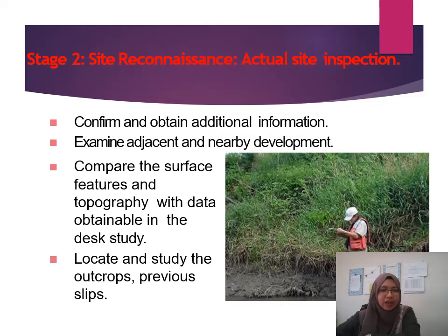So he can check and identify the actual features of your site. Locate and study the outcrop, the previous slip, and so on. So he will observe all of the detail that he can see on your site: the topography, the type of the site, and so on. And then he can identify the size or type of exploration plant or equipment that is accessible to your site.